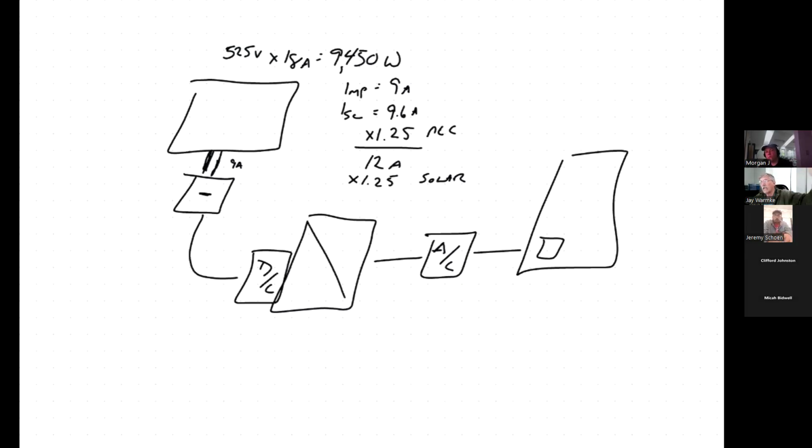At the outside edge of the Earth's atmosphere, it's like 1,360 watts per square meter. So if you get a nice clean day, like here in Southern Ohio, where the air is pure and people are kind, right? Then you're going to get higher. So we take the second safety margin times 1.25, and now it's saying 15 amps. So our wire better be able to handle 15 amps.